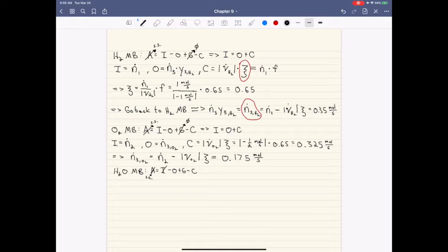We don't feed in any water into the system, so the input stream is equal to 0. We do have water leaving the system, the output. Water is generated, so our generation term stays, but water isn't consumed, so our consumption term is also equal to 0. And so what we get here from this relationship is that the generation is just equal to the output.